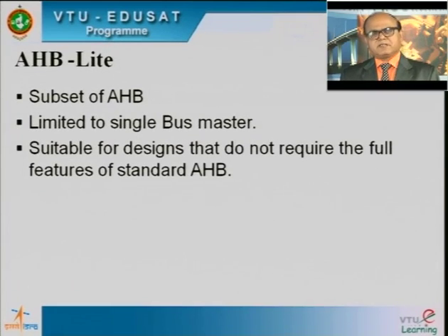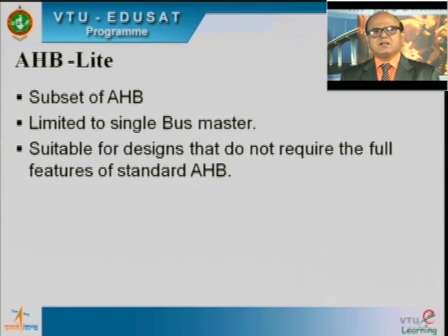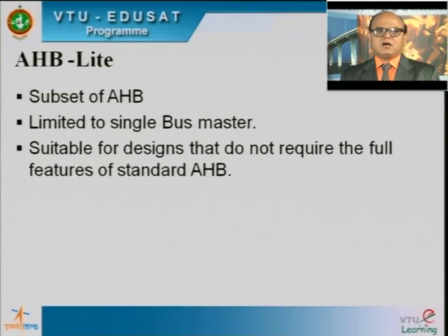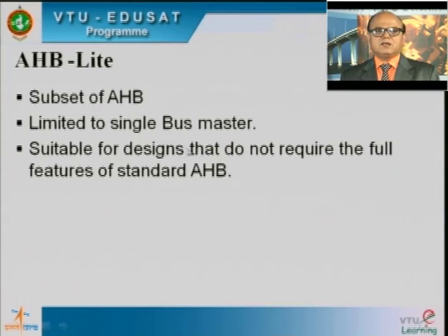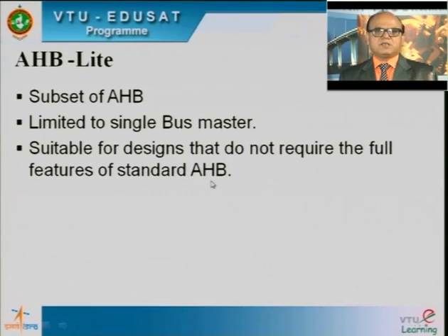Coming to the AHB Lite, the second variant, it is a subset of the conventional AHB. When I say subset, it is not a full-fledged ARM high performance bus. It has a limited single bus master and is suitable for designs that do not require the full features of standard AHB. So when I have an embedded system application where I do not require all the features of the standard AHB, in such a case the AHB Lite will suffice our requirement.